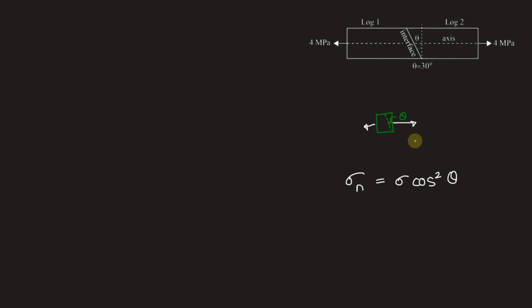So first, in the derivation of sigma n, first the forces are being calculated using the stresses, and then the forces are transferred on the plane, and forces are then back calculated to stresses. That is how this formula is derived. But for the exam, you should remember the standard formula for transforming uniaxial stresses on planes inclined at angle theta. This theta is taken with the vertical. With respect to this plane, the theta is being measured.